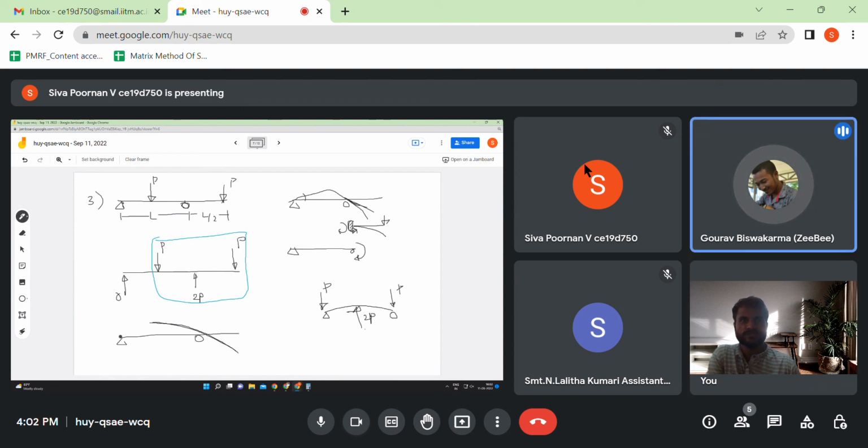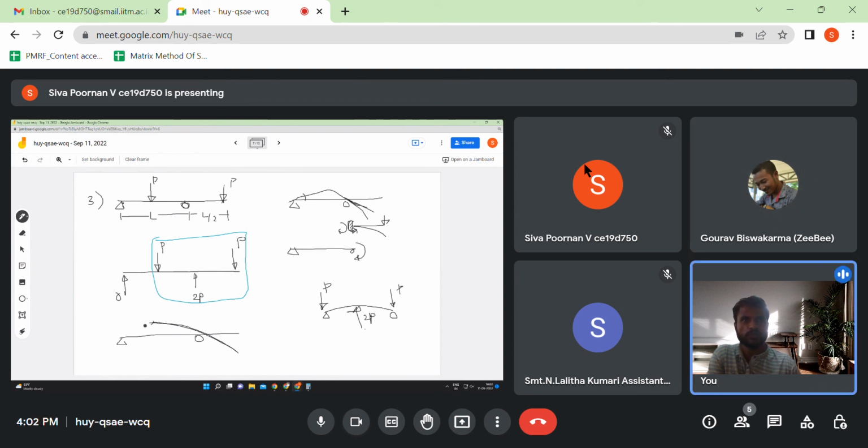We can draw a tangent there. Actually, the tangent at this point should be towards this point. So it should not be curvy, it should be a straight line, and that tangent should be there before drawing it. So you should be very careful when you draw this problem. It's a straight line because when you start from here, you see that there's no bending moment. So we know that it's a straight line. From that straight line, that tangent, you have to keep it up and start perpendicular, and you have to draw the bow. That's how that bow should be.